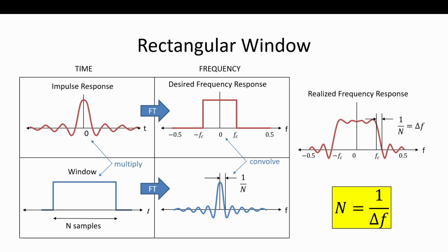We want to go out to infinity. Now, we can get as far as we want in terms of our processor having the resources to compute it. And so then we multiplied it by a window. We multiplied it by a window and made it causal and realizable. So multiplying in the time domain is convolution in the frequency domain, and it goes vice versa. Multiplying in the frequency domain is convolution in time. We covered that.